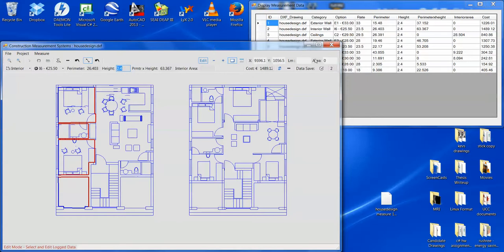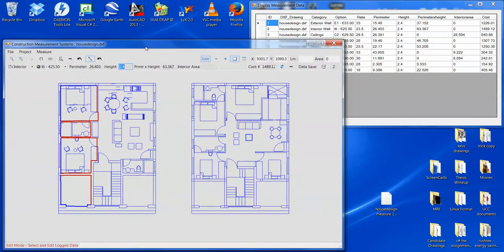We're on index 2, which is interior walls. The option is a screw fix 12.5 on fire resistant plasterboard to existing timber stud partitions. The perimeter is 26 linear meters. The height is 2.4. Now the save process for measurement files carries over the appropriate scale. So if I scaled this drawing yesterday while making this quotation and logging all these measurement groups, the scale is carried over and I'm working with the same scale, so I don't have to rescale or recalibrate the drawing.